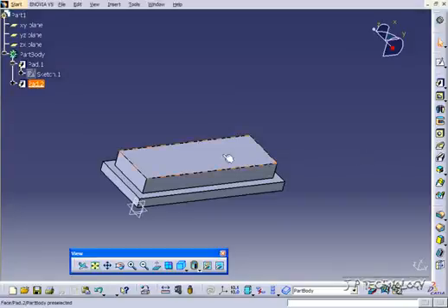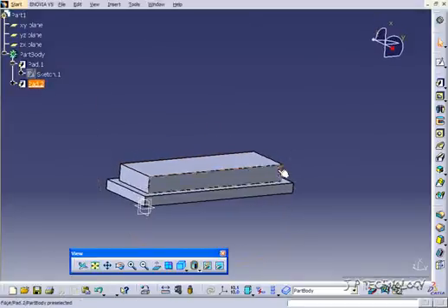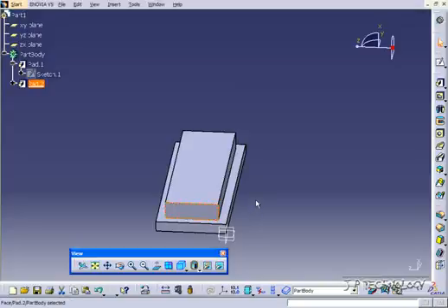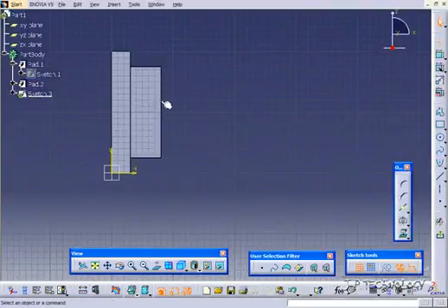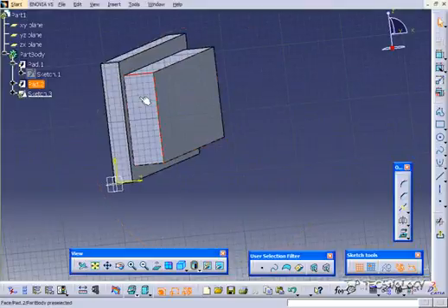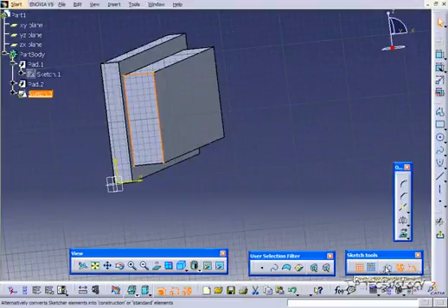So to start off, let's start making some sketches to make our slot. First off, we're going to make the profile. So let's click this face here, click Sketch, and let's click the top line here, press Control, click this line here, and this line here, select them all, project them out, and turn them all into construction elements.